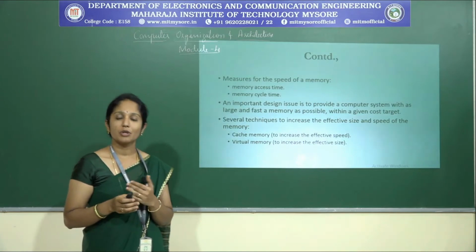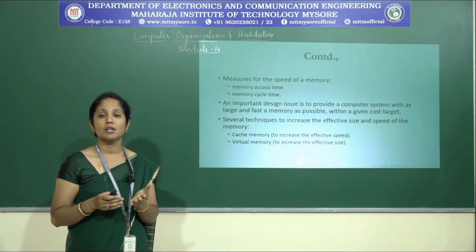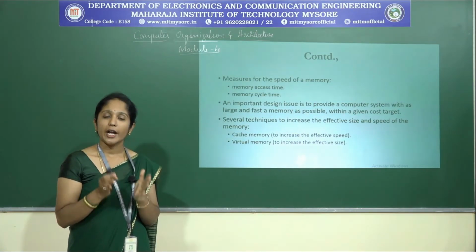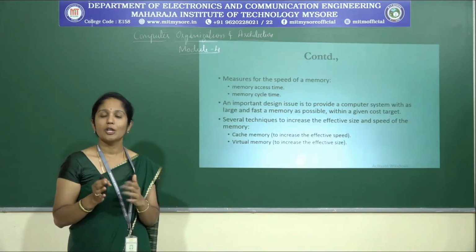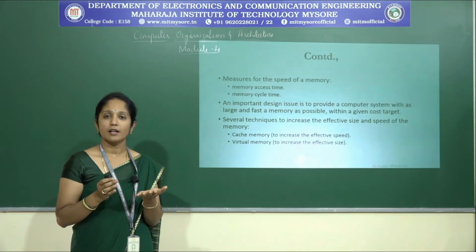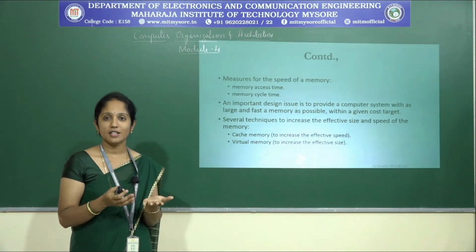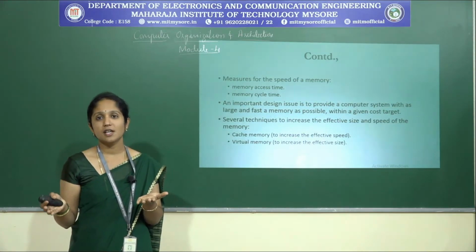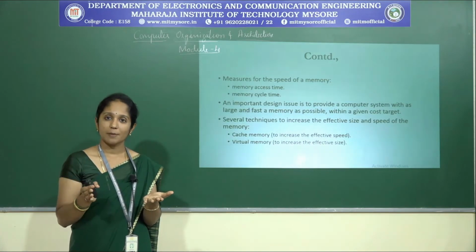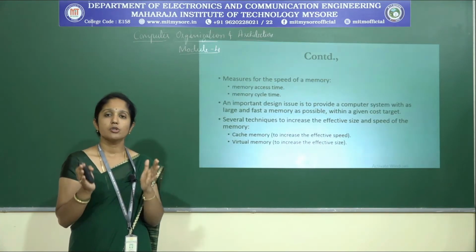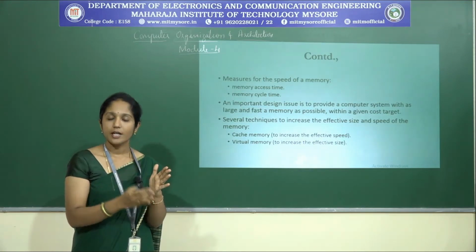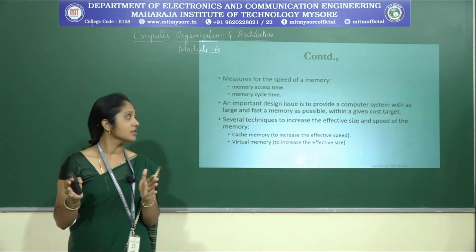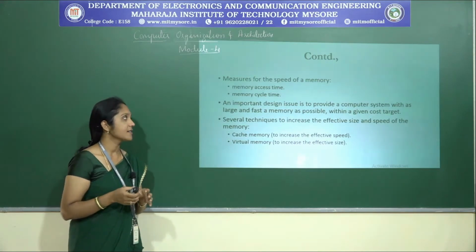If you consider a read operation, we can say that it is the time between the Read and MFC signals. We know that the Read signal is asserted to initiate the read operation, and the MFC signal is asserted after completion of the read cycle. Therefore, it is the time between the Read and MFC signals. So this is the memory access time.